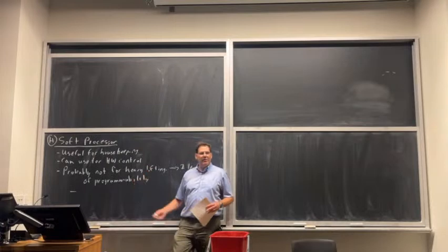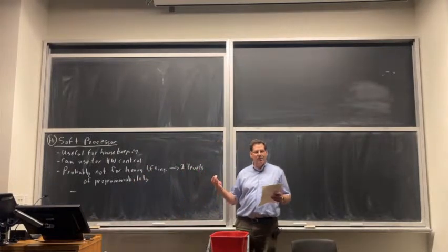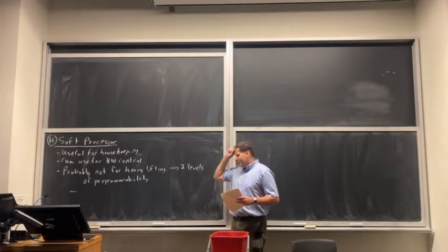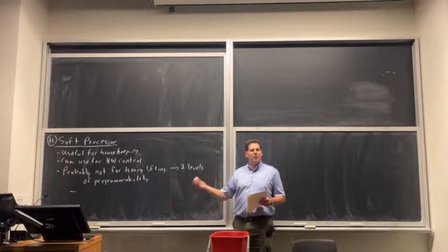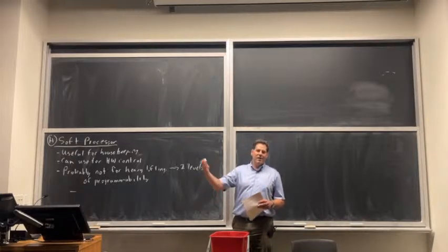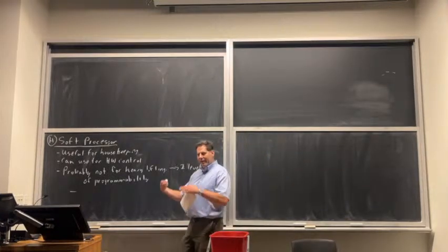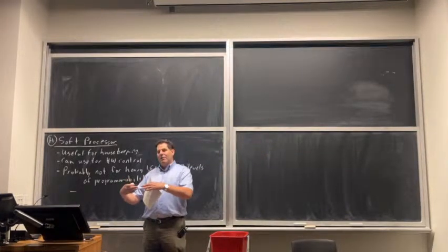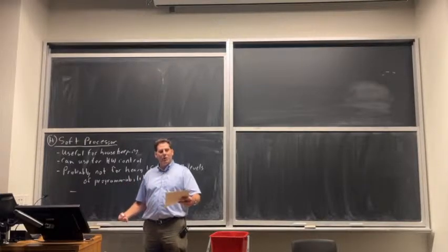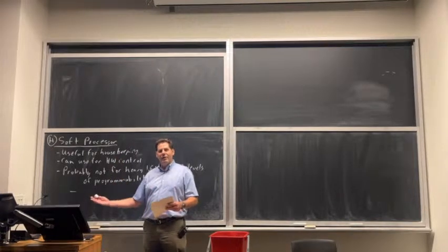What do you think it is? Like 1.5x in terms of the amount of throughput I can get per unit of silicon, right? So let's multiply the area times the clock period. That tells me the opposite of how much throughput I can get through the silicon, right? If I'm smaller, I can make more copies. If I can run faster, I get more done.